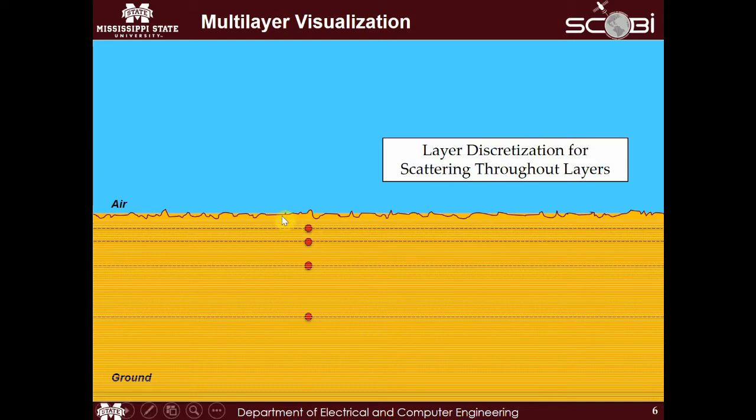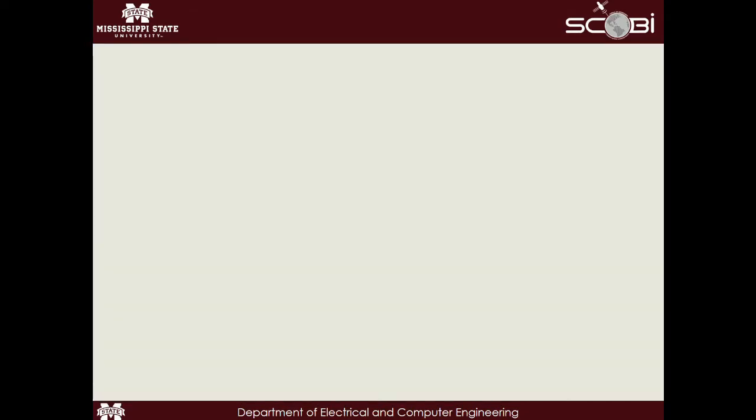So at every millimeter down from the top of the layer down to the very bottom, there is going to be some value assigned for a relative permittivity value within that soil moisture profile based on that input. As you change that, you can change the, I guess you would say, resolution of your soil moisture profile, but that's just what we've chosen for the default input.